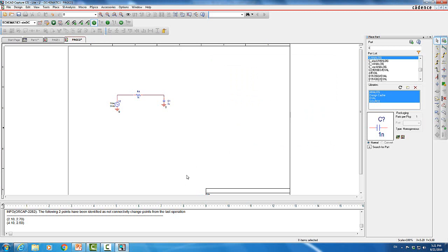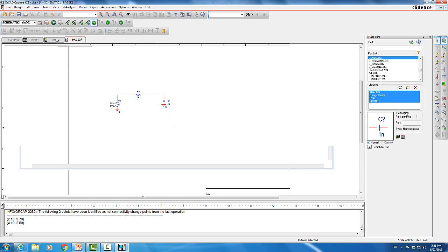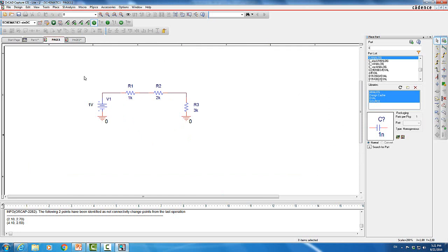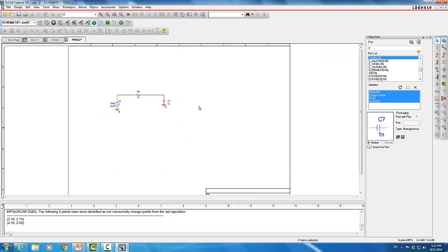So now we have remodified our simulation from DC sweep to AC sweep, and we have removed the probe on page 1, so nothing is going to be measured here. We're gonna add the probes here. All I'm gonna do is add the probe at the output, basically to say that we're gonna measure the output voltage as the input voltage changes on a logarithmic scale.